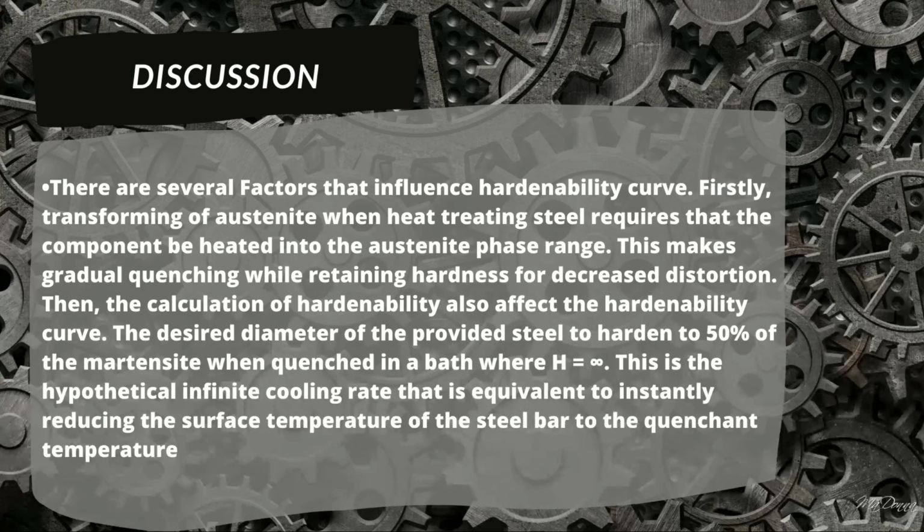The desired diameter of steel provided to harden to 50% martensite when quenched in a bath where H is equal to infinity. This is the hypothetical infinite cooling rate that is equivalent to instantly reducing the surface temperature of the steel bar to the quench temperature.